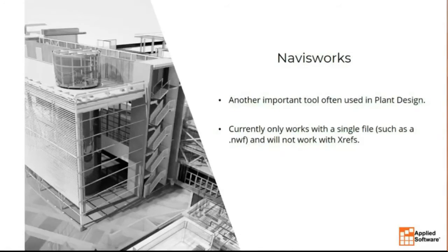They don't do well with multiple references and relative references. You have to go with an absolute reference, or you've got to be careful. With Navisworks, that's no exception, so it only works with your single NWF file. We can go into that next.